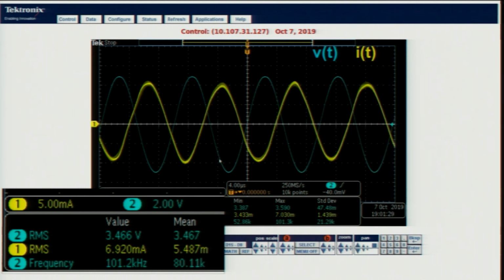This is not what we saw when we considered the same experiment with a high bandwidth current sensor. What is actually happening is that this current sensor itself, at this frequency, is introducing some effects of its own. So we see a phase shift of 180 degrees between current and voltage, which is obviously a spurious reading. One of the things you should remember is that for the measurements you make, you should choose the correct bandwidth of all the sensors.